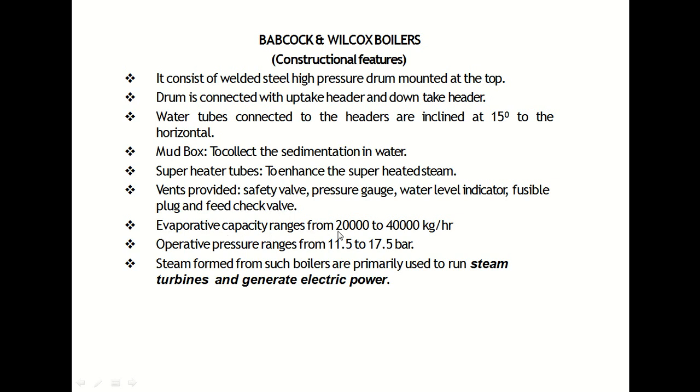It has an evaporating capacity ranging from 20,000 to 40,000 kg per hour. So it has a large capacity compared to the fire tube boilers. Operating pressure ranges from 11.5 to 17.5 bar. So this is a low pressure boiler.